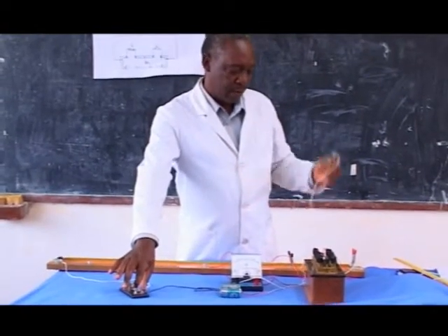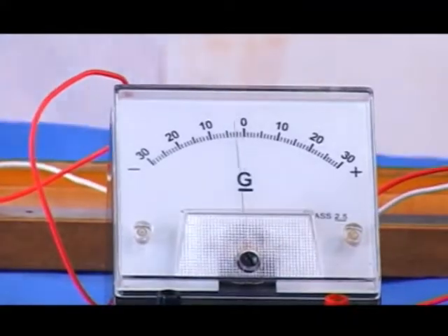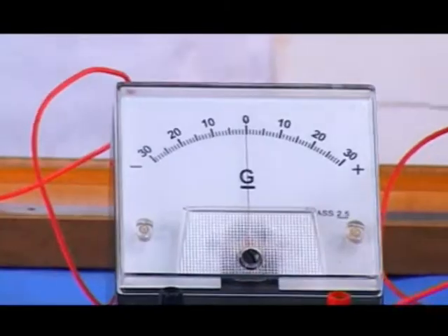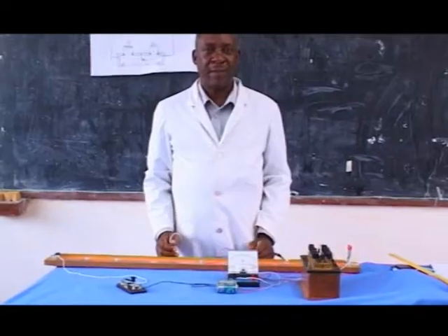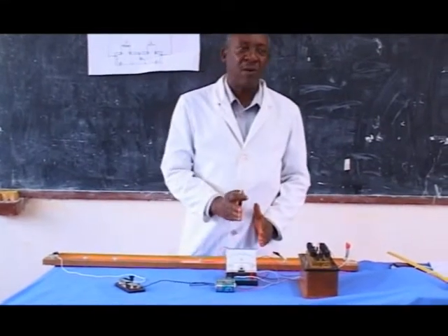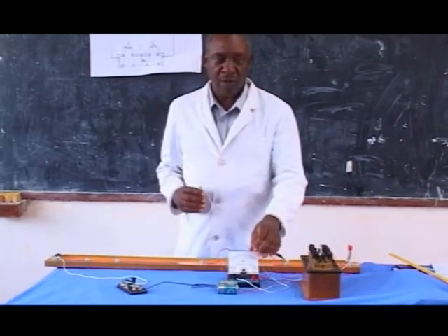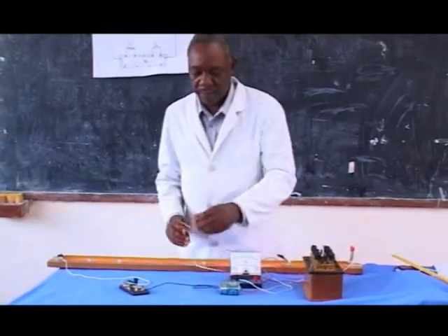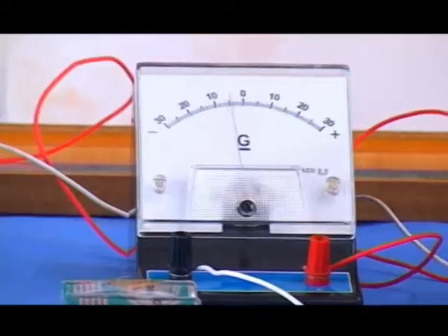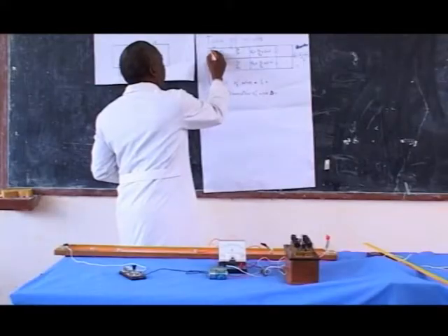Touch on the left hand side of the meter bridge; the deflection is there. Touch the other part. Now narrow the interval so as to get the zero balance, the balancing point, which we call X.